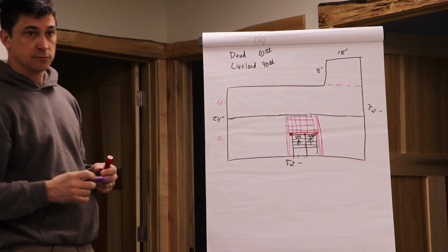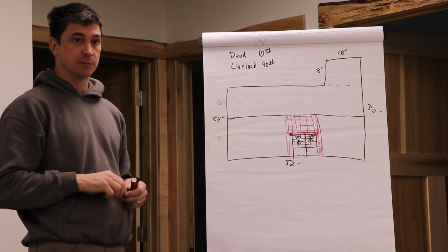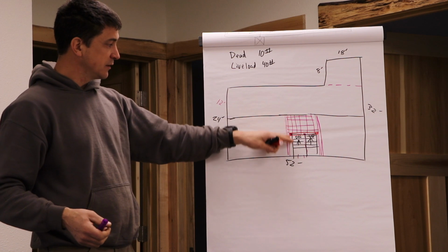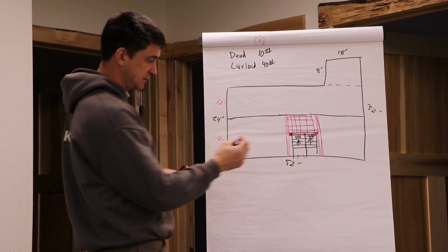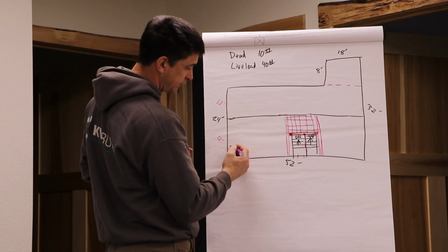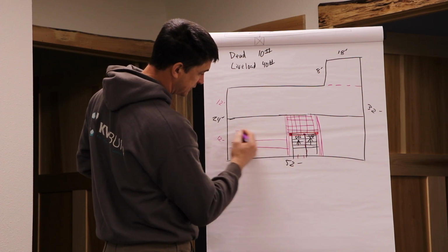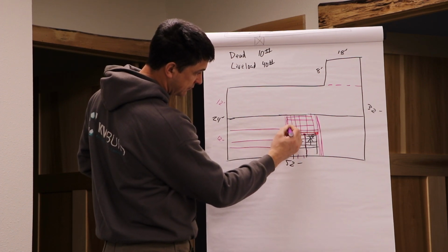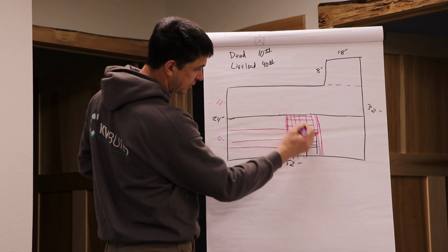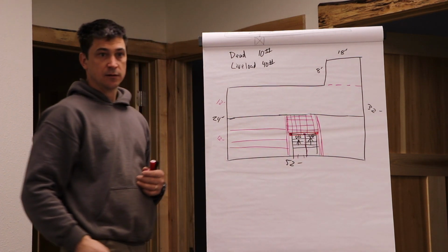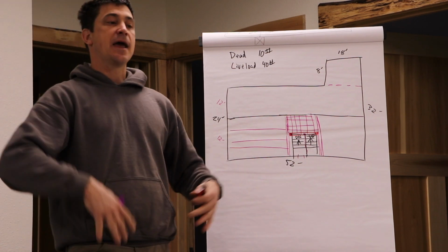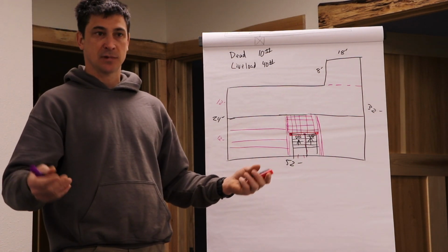You could. So that's another option. You have to get your layout really exact, because you could run all your sheathing on this floor, and then when you get to this, you could end it in the middle of this beam and then run this stuff this way. I try to avoid that just because it adds to your time when you're building.